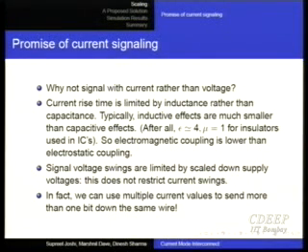We had looked at low swing voltage signaling, and we found that by limiting the swing, we can gain quite a bit, both in power and in delay. One nice thing which we didn't discuss last time was that this optimization of buffer insertion remains with the low swing signaling.